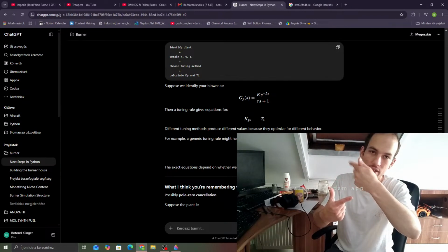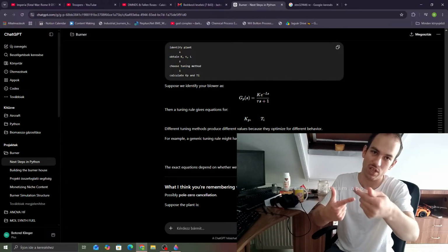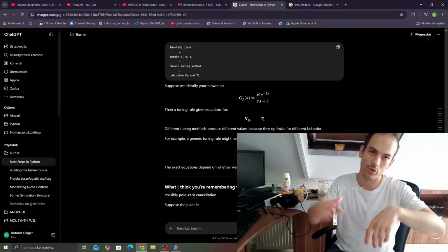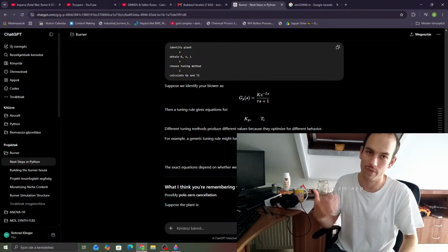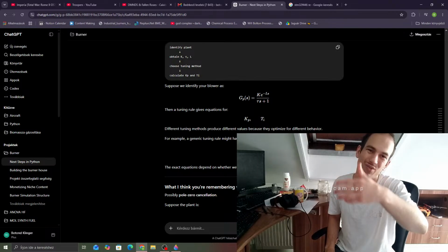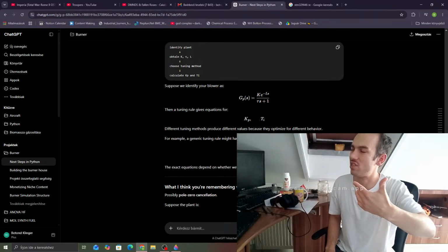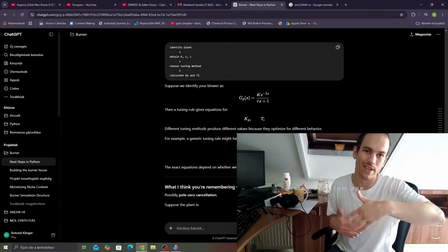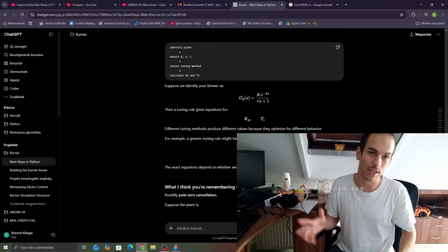activate the controller to use the PID, because there is a baseline fluctuation that we don't care about if the pressure goes down by a little bit. You don't want to over-constrain it by always running with the PID controller.